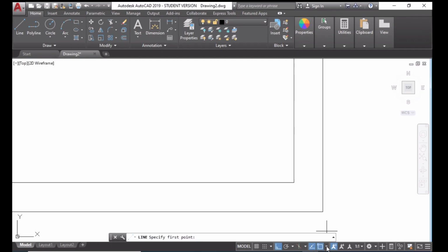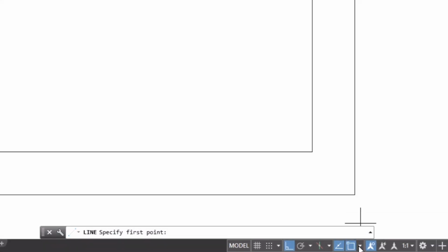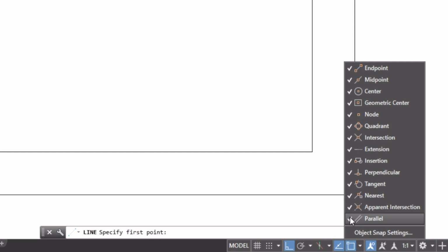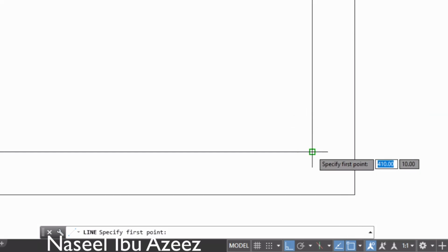If you are not getting snapping, the one thing you should do, come over here, there is an option called snap cursor to 2D reference points. Turn it on, and I'm suggesting you turn on all the snapping options because it will be useful. Once you become an advanced user, you can turn off certain things and turn on whatever you want. As a beginner, you turn on all these snapping options. If you turn off the snap, you will not get this point easily.